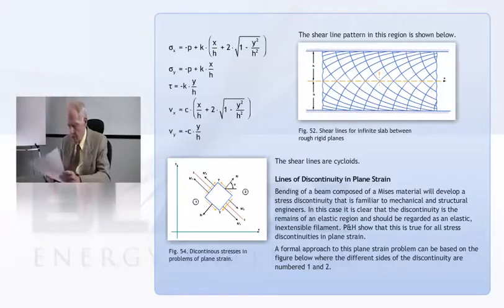What you come up with is shown in that picture in the middle of the page, where the shear lines have very nice looking shapes, and in fact they're cycloids, a set of orthogonal cycloids, and the equations give what the pressure is to do the pushing, and you can see that you have a solution there.